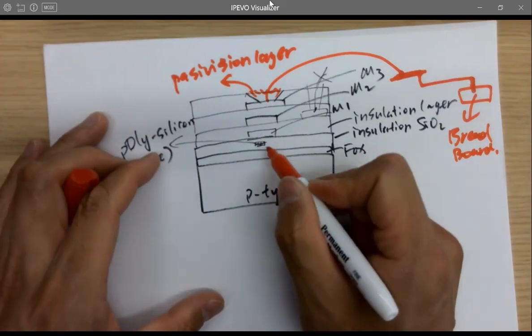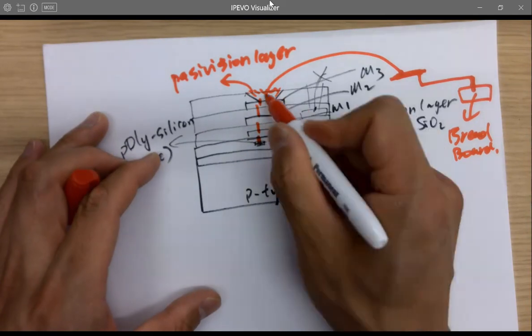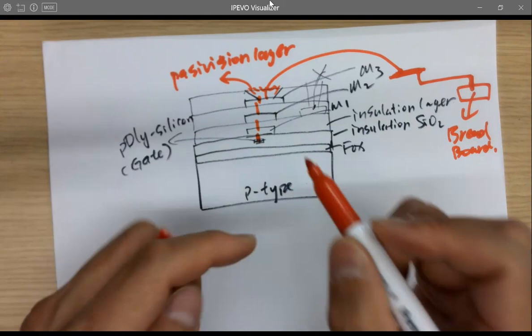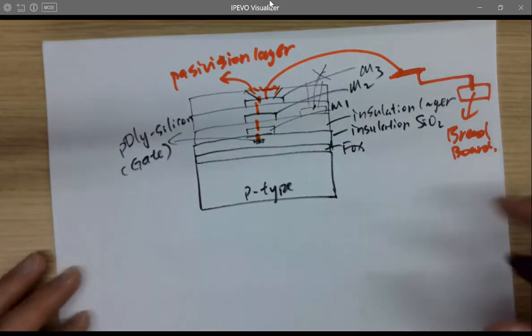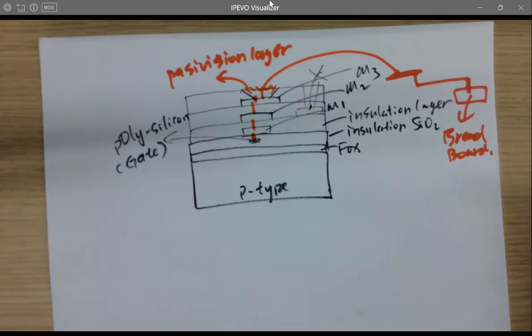If you need a signal from the transistor, from the gate, you need a via to metal, and then open up the gate or open the transistor's channel to run current in the channel. Make sense? I'll keep talking about the CMOS layers next Monday.